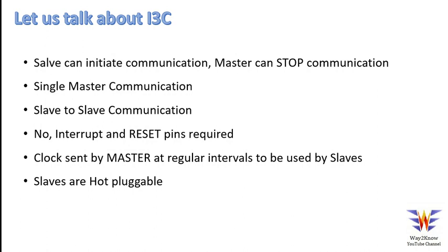And one more advantage is basically the slaves are hot pluggable. Whereas in I2C, unless the master knows what the slave is, what its configuration is, it cannot talk. But here, a slave can come in at any point of time, and then the master can assign an address to it and communicate as per the requirement. So a very flexible communication mechanism.